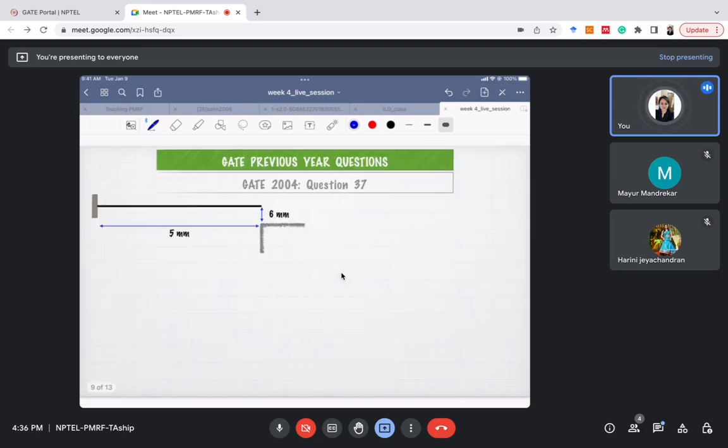Now in the second case, when W is equal to 100 kilonewton per meter, let's calculate delta B. Delta B from the standard deflection formula will be equal to WL^4 by 8 EI. What is the value of W here now? W is 100 kilonewton per meter. Please solve this for me.